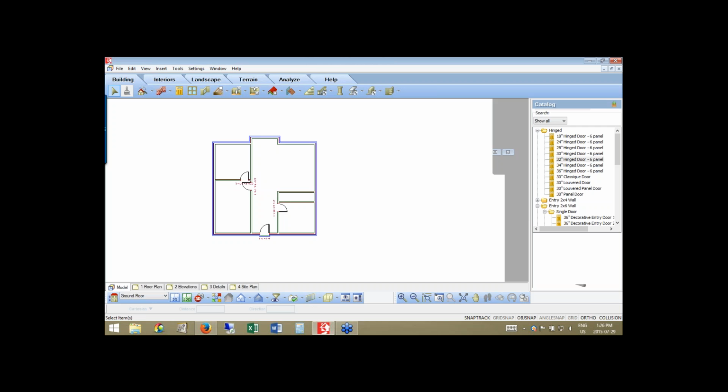If a door goes in, or perhaps the swing is wrong, so let's take a look at this door here in the lower right. I come into the room, I face a wall. I want to come into the room and face the room. So I select the door. I right-click to reveal options that I have for that one door, and I tell it that I want it to flip the swing. Okay.